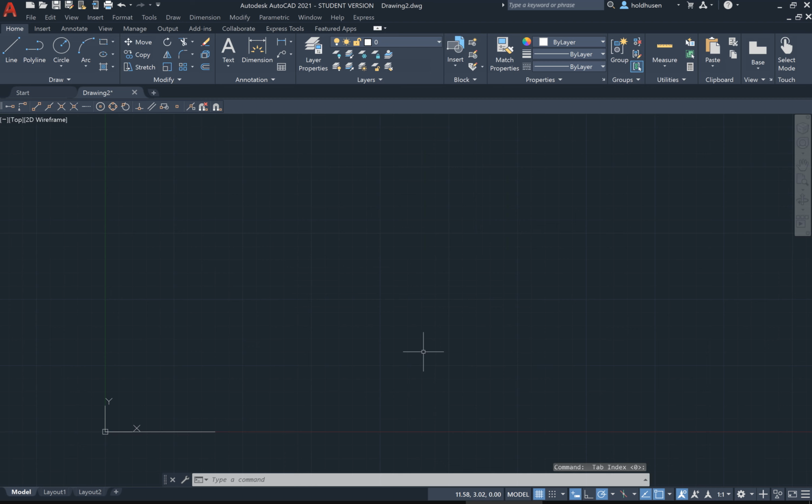So now that I've set that, if I want to create a new line, again, it says specify the first point. If I go right here, let's say I want to go straight up 2. Well, remember, now I've got absolute coordinates in there. So I'm actually from the origin over 4, comma, 2, like so, and I can hit enter, and it puts the end of that line 4 over and 2 up from the horizontal.